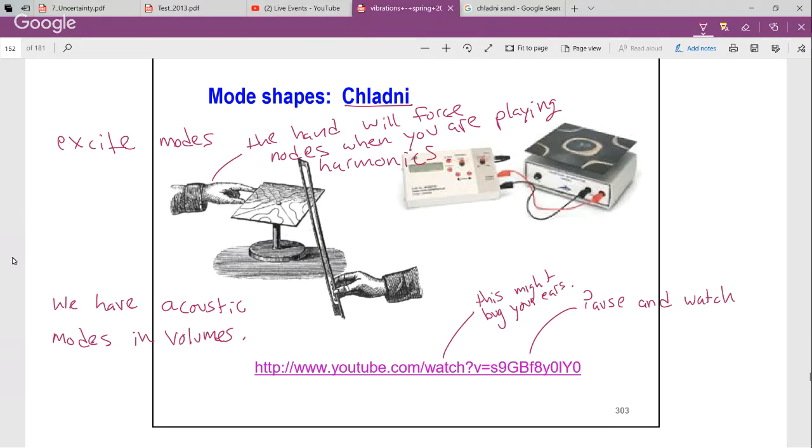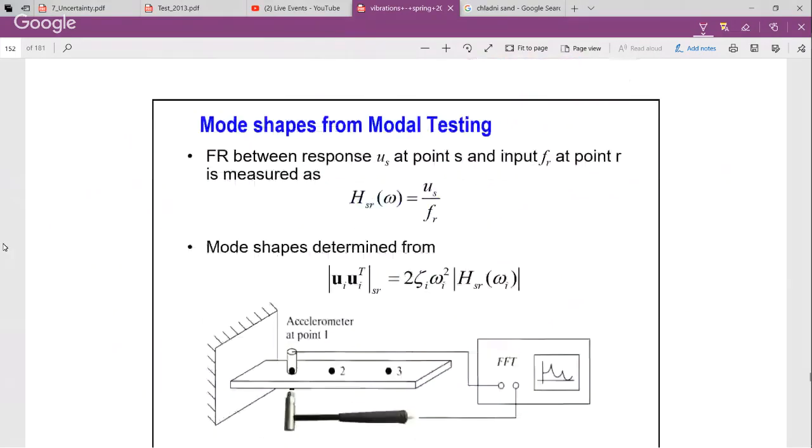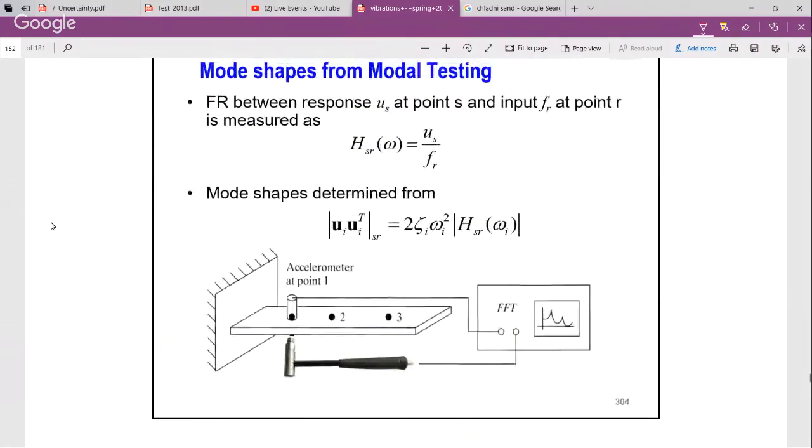If you didn't want to actually put sensors on it, we're trying to do everything noncontact. Microphones to measure frequency response rather than accelerometers, and then we use very small amounts of very fine grain sand to validate our final results.